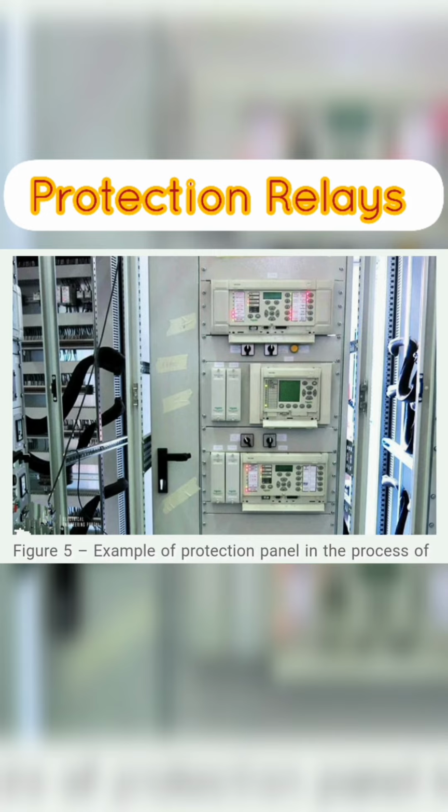Note: it must be able to select between those conditions for which prompt operation is required and those for which no operation, or time delay operation, is required. And it must operate at the required speed. How well any protective relaying equipment fulfills each of these requirements must be known for each application. Note: the ultimate goal of protective relaying is to disconnect a faulty system element as quickly as possible. Sensitivity and selectivity are essential to assure that the proper circuit breaker operates.